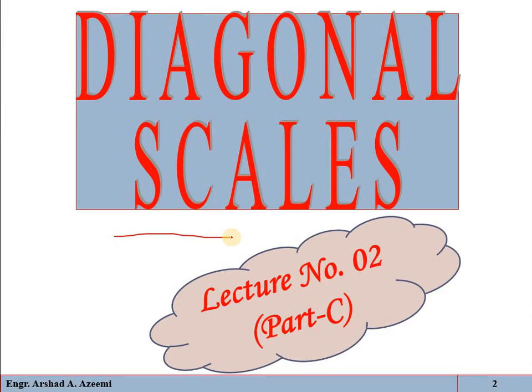We have different types of scale, for example the engineer scale, the graphical scale, and the representative fraction. We have already discussed that with respect to time, when the drawing shrinks, there will be error if you are expressing the scale in the form of an engineer scale or representative fraction. But with the graphical scale, if shrinkage occurs in the map or plan, the shrinkage will also occur in the graphical scale, so there will be no error in the conversion of drawing dimension into actual dimension.